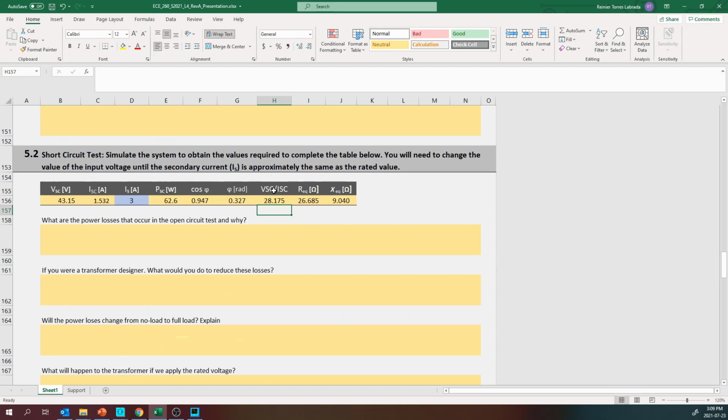So you don't have to change anything else in the circuit. And what you need to do is to record these values and change the load that you put in. So that resistor that you added on the secondary, you need to change it until you see the nominal secondary current flowing through that resistor. And at that point you have the load, you have the voltages, and from that you compute the voltage regulation. And of course you need to write here the equation.